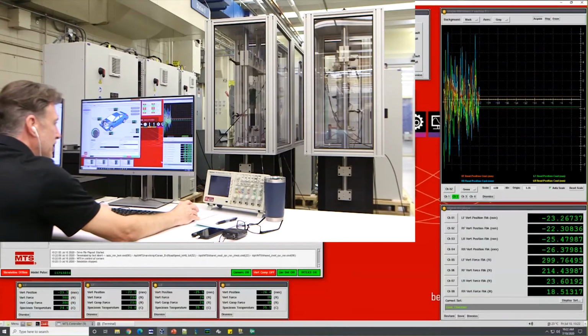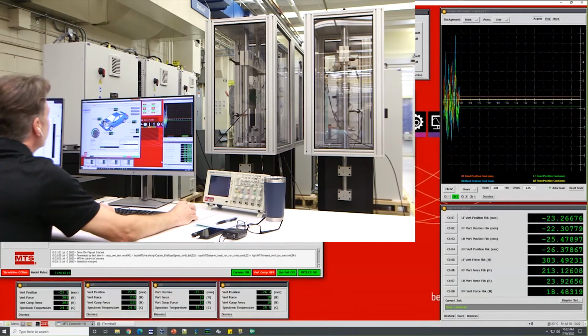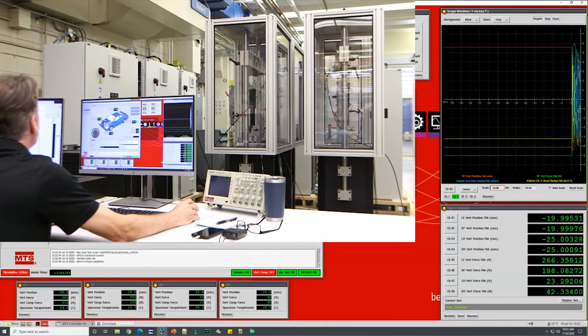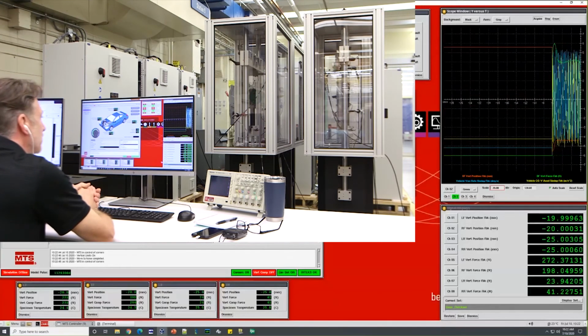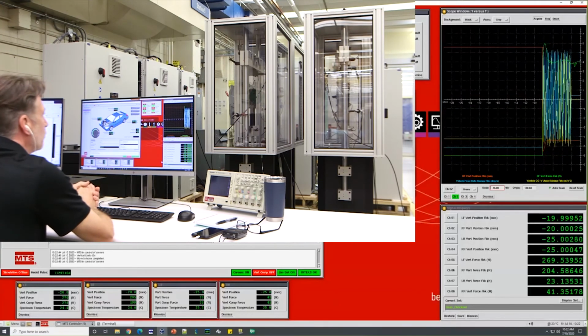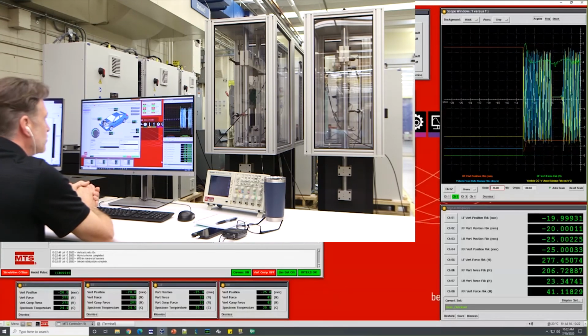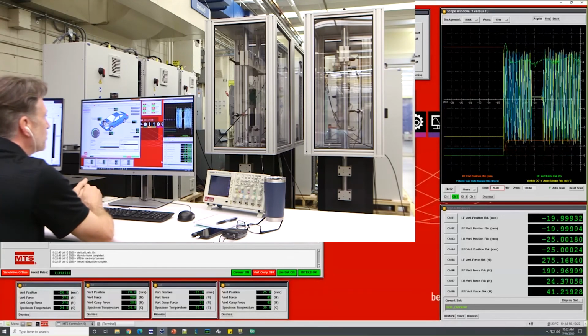Ford presented in his introduction that we would run through 3 different events. The next one we're going to run is a double lane change. So I've queued up the double lane change. I'm going to select this test sequence associated with that and push run. Now again, what you can see on the scope, we'll be turning back to the machine quickly, is us stepping through that sequence again of initializing, doing the equalize, making the source switches, and then starting the simulation.